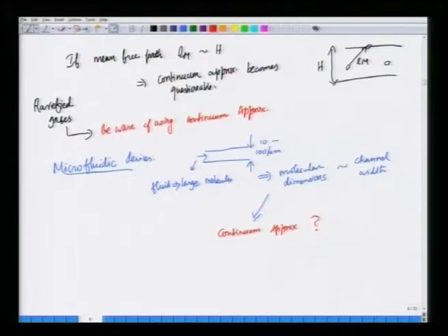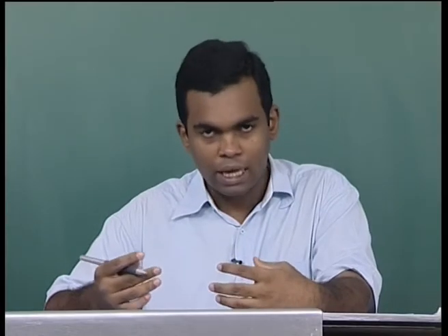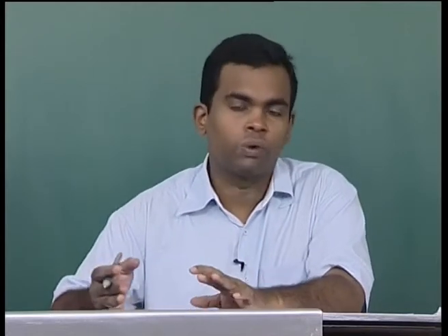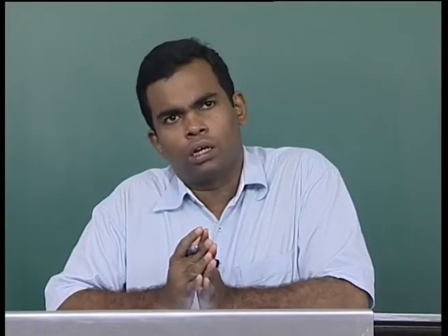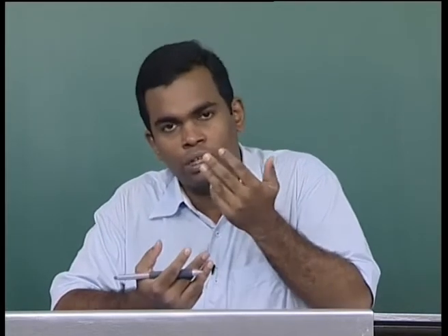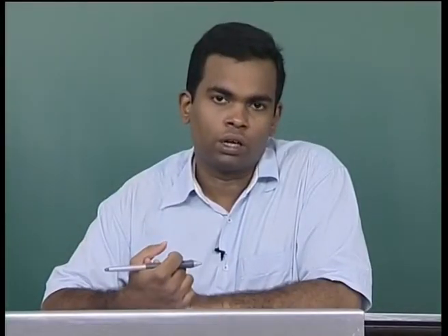So there are cases where the molecular length scales become comparable to the macroscopic scales, as in rarefied flows or microfluidic flows. In such cases, it is not obvious whether one can successfully use the continuum approximation, and there are always other more fundamental approaches where one takes a full molecular approach, with full molecular detail, but those are obviously much more involved, and they are specific to the kind of problems that one addresses.